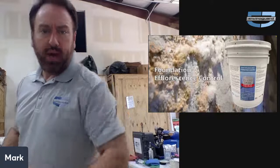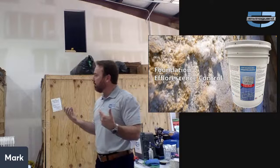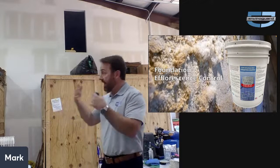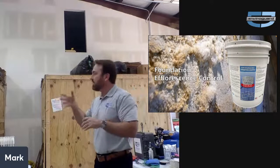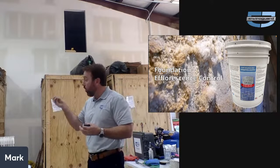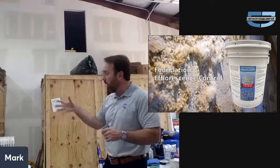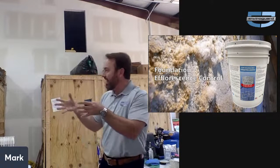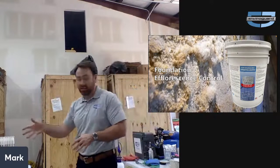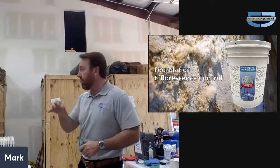And then along with that, we've got some complementary products. One of them would be Enviroseal. Efflorescence forms because you have sodium hydroxide, calcium hydroxide that is present in all concrete mixes. And because it's water soluble, over time, the moisture that's coming from the positive to the negative side of the wall is drawing that calcium hydroxide to the surface, and those deposits form, right? It's a mineral deposit. That can be prevented by using our silicated Enviroseal product.